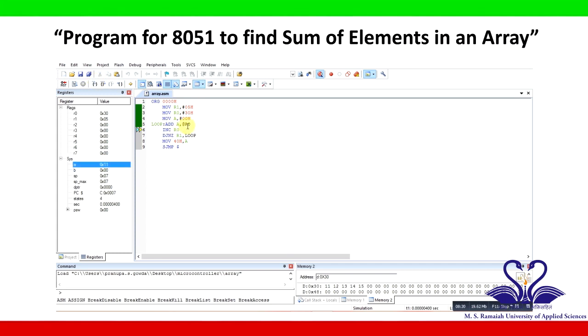Next step, ADD A, @R0. @R0 is indirect addressing mode, which means that R0 is having 30H. @ means the memory whose address is in R0. So in 30H memory location, whatever data is present will be added with your accumulator and the result will be stored in accumulator. As you can see, A was having 0 and in 30H memory location we had the value 11.